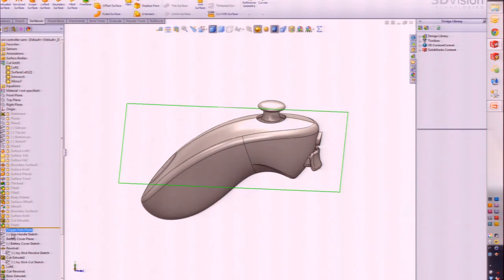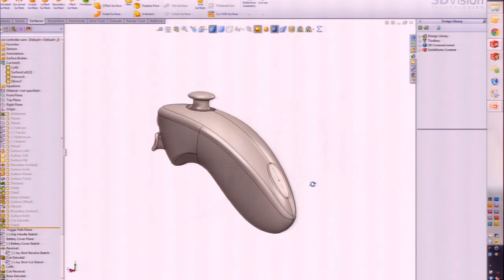Yeah, the question was, do I normally add it to the separate files rather than this file? And the answer is yes, because SolidWorks is RAM dependent, and the more features, the more surfaces, all that you've got going on in one file, it's going to start to slow down. So separating these out at a certain point, when you no longer need those references, like I don't need to know anything about these other bodies to add that shell feature. Those are the types of features I'd like to add elsewhere.